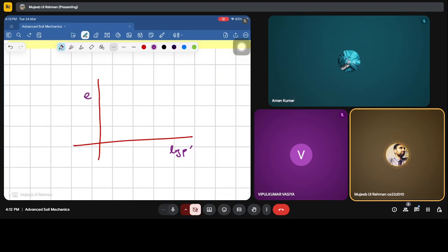When I start loading it, the void ratio and the p at the critical state, at the final state, that mean effective stress is the state of the soil which it has achieved at the current time. I'm loading the sample and recording the values. So I got this point. This stress state of the soil is experienced for the first time. Now, the second time I started the test, I got e versus log p with this point. Similarly, I got this point.